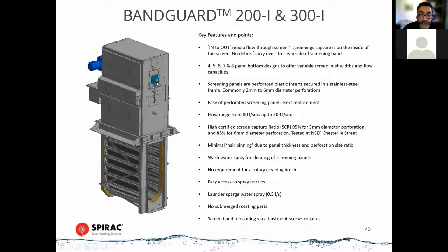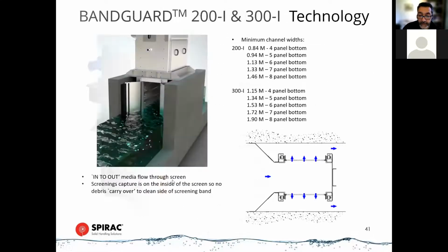Chain tension, as with this screen and the other screen I mentioned, we have these screw jacks on either side, so this allows us, as the screen wears and the chain does elongate after a while, the screw jacks allow this, by means of this screw here, to lift the drive shaft up, and then tension the chain again, so that you get maximum efficiency and you reduce wear at the bottom because the chain's sagging. And then you can incorporate an integral compactor into this screen as well.